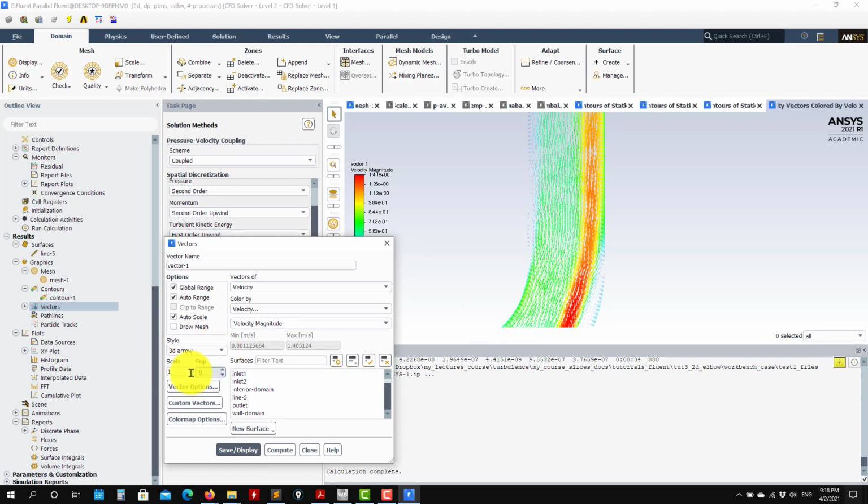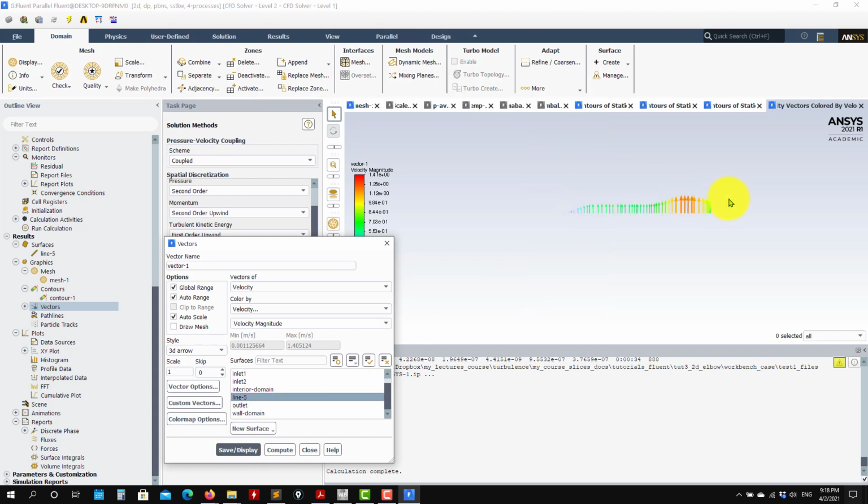So here you have these options to skip. Now, so you put 5, you are skipping 5 there. Okay, so be careful now. Depends, you know that you have a lot of cells. This can crash your computer. Okay, so just to show you something that, well, I will show you in the standalone more advanced post-processing.